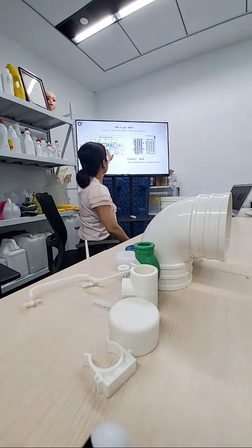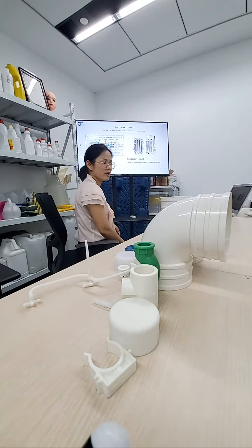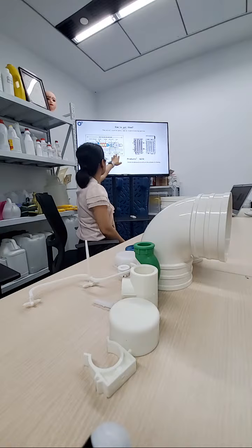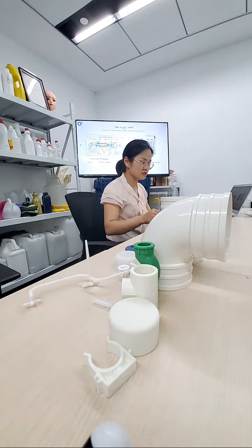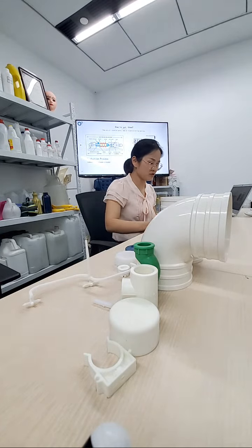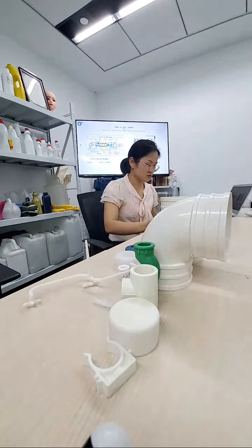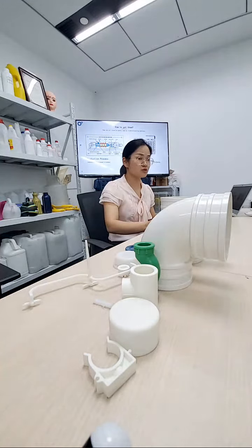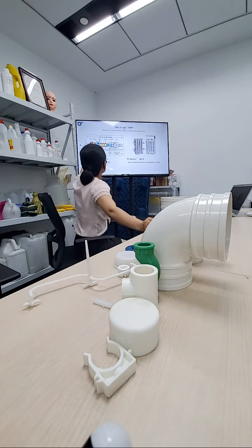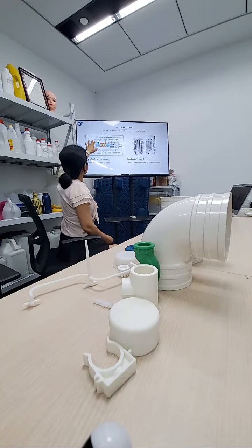Injection machines totally have two main parts: an injection part and a clamping part. The injection unit consists of three main components: screw motor drive, reciprocating screw and barrel, heater, thermocouple, ring plunger. You can see all these parts in these photos. This one is plastic granulates. This is a hopper, this is a heater, this is a screw, this is barrel.